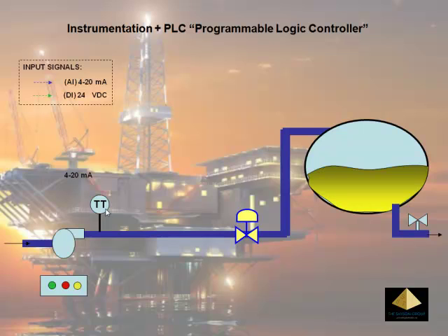This time, the temperature transmitter will convert the physical form of energy into an electrical form in 4 to 20 milliamp current format. The flow transducer will also be attached to a device that will convert the flow into a current, which is 4 to 20 milliamps. Thus, this will now be called the flow transmitter.